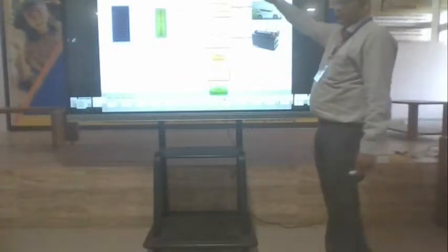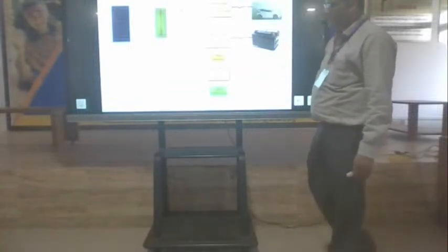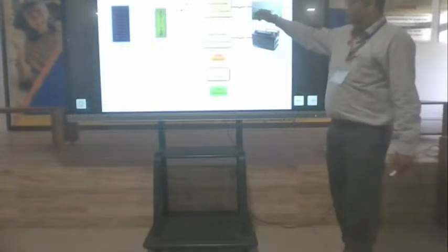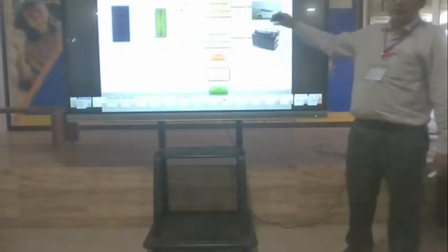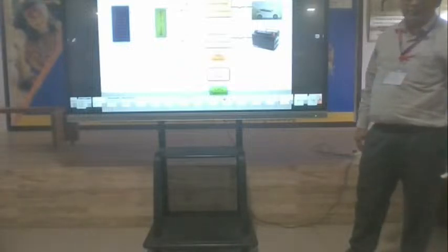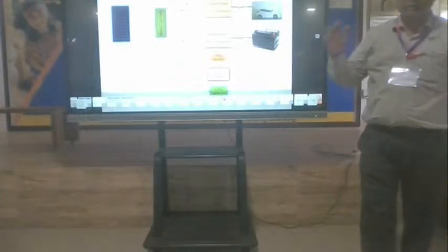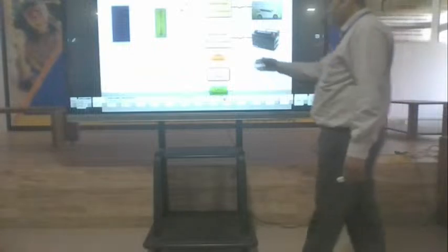So we have seen that various resource persons discussed that this EV charge controller is required for the maintenance of the state of health and state of charge, SOC and SOH. The current and voltage values are continuously taken from the electrical vehicle, the health is monitored, and based upon that the voltage from the DC-DC converter is controlled. Here you have the bidirectional converter, and here the unidirectional converter.